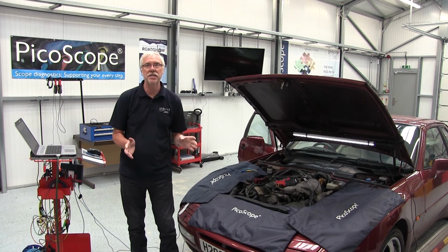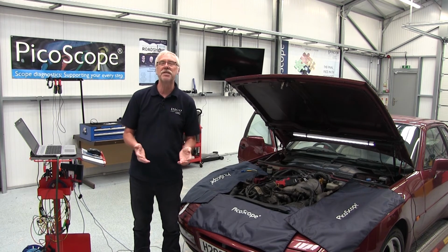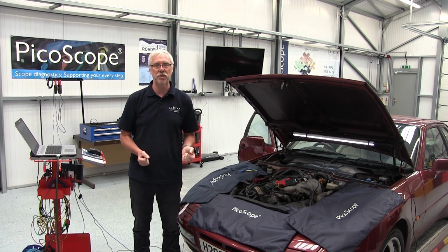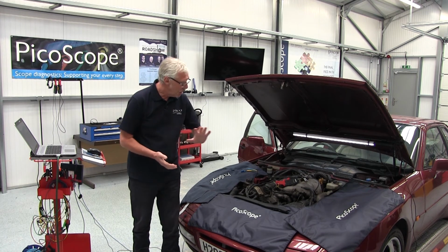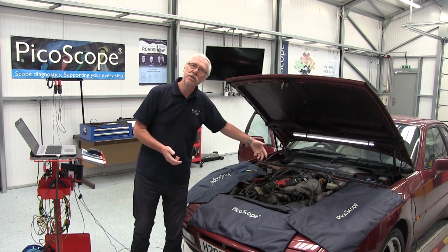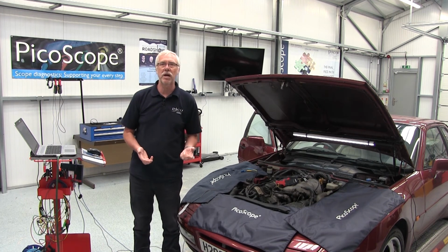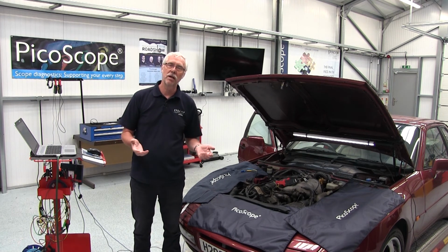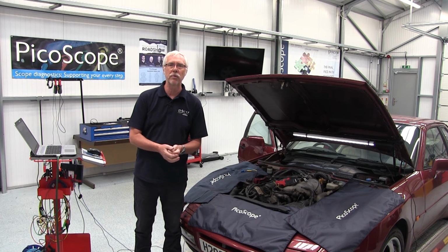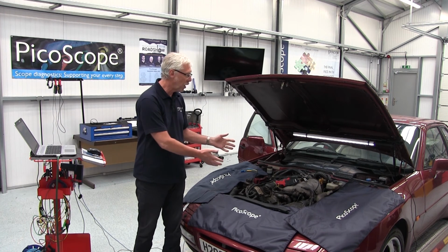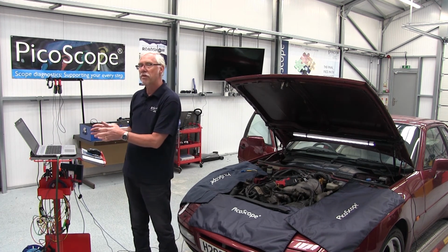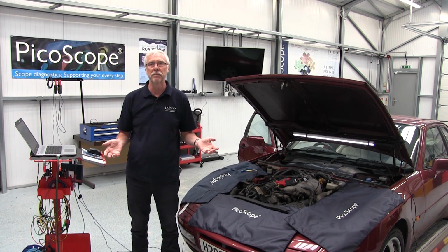But right at the bottom of our test is further guidance. This is good information and it's the notes from our automotive specialists on how they did the test, what they did. It'll tell you about the system, about the components, how to connect, and also some diagnostic info to help as well. And then right at the very bottom are our diagnostic trouble codes, just the generic ones in this case. So we've got our waveform, volts and current from injector number 1 on screen, and we've got some help there for you as well.